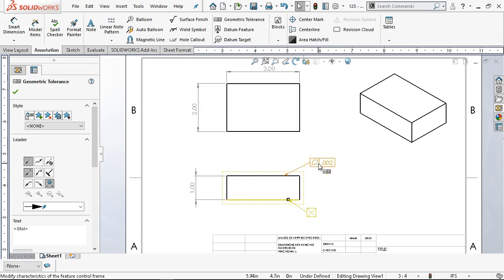So make sure I'm getting my terminology correct here, because the flatness and the tolerance on the 1 inch, my tolerance zone at its max would be 1 inch and 10 thousandths. All right, at 2 decimal places, which I just caught that I didn't change, the plus or minus 5 on the top and the bottom now adds up to the same tolerance zone that I have on the dimension.